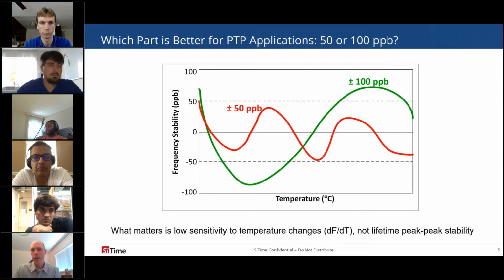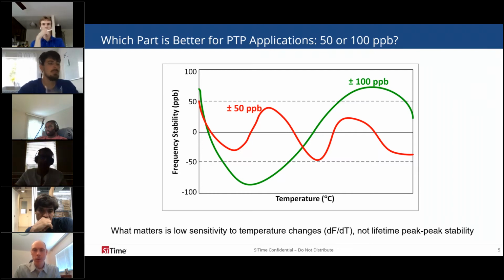And when evaluating a precision oscillator, the most advertised specification is frequency over temperature stability in units of ppm. People sometimes just refer to that as stability because it's so common. For example, people will talk about a 1 ppm oscillator or a 0.5 ppm or 100 ppb. This is the frequency over temperature stability, and it's the first thing people typically think of when selecting a precision oscillator.